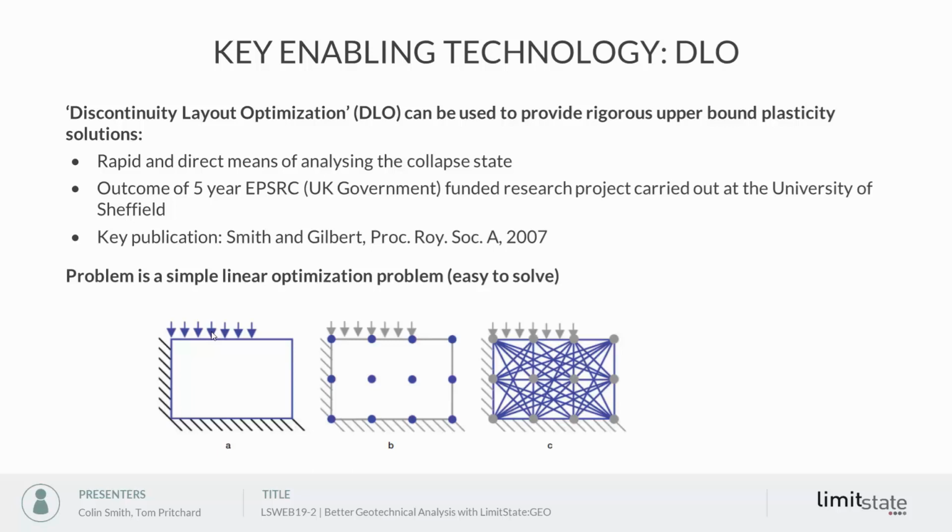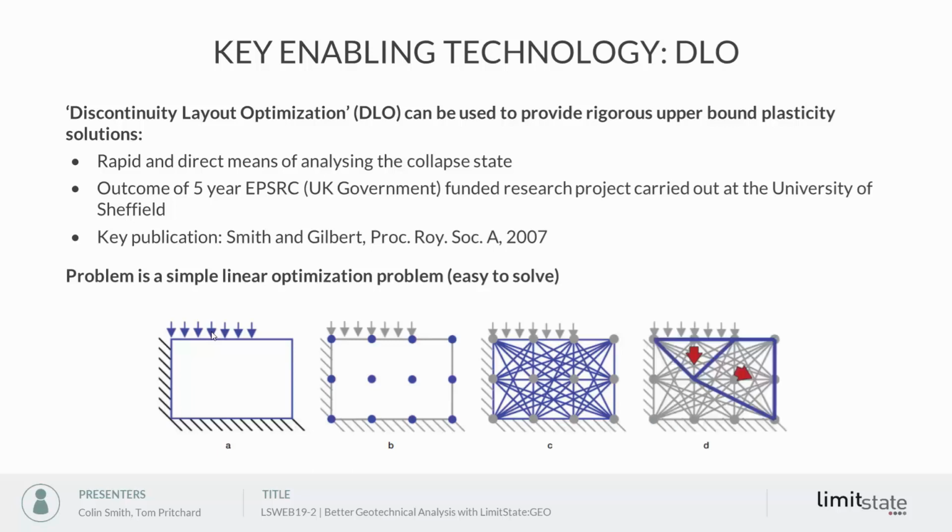So here we've got 12 nodes, so we've got 12 times 11 over 2, 66 connections. Out of that, the critical set are these 6 slip lines, and that gives the most critical collapse mechanism, or the one that essentially dissipates the least energy. So it's essentially an optimization problem looking for the minimization of energy dissipation. This is a very simple problem with just 12 nodes.